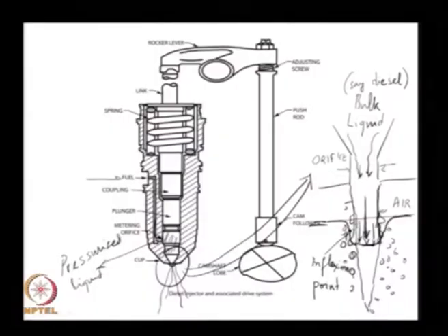That inflection point is sufficient to cause this flow field to be unstable and cause drops to be sheared from the side. So, I have a cylindrical column, it breaks up. This is a basic principle of operation of a diesel injector.